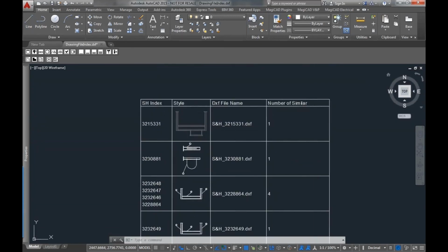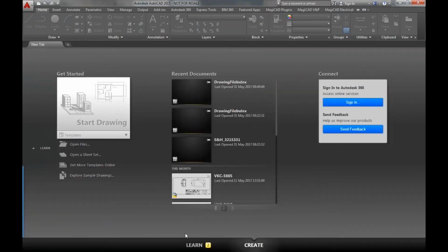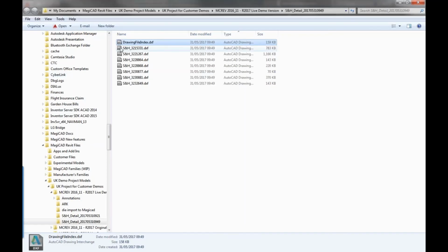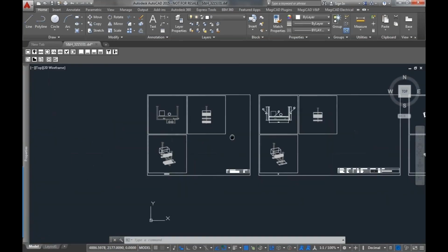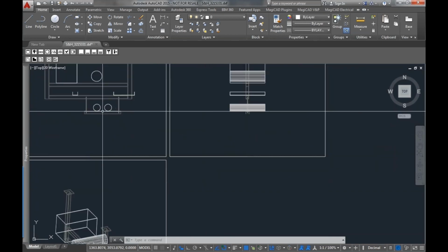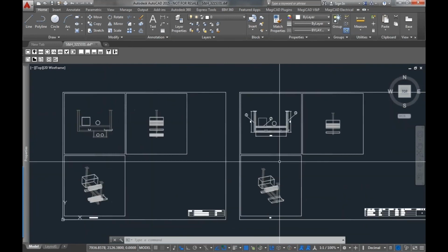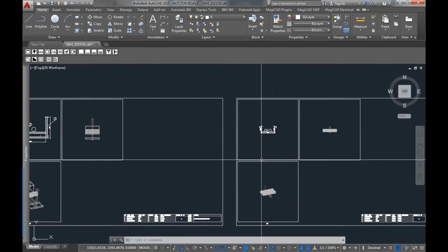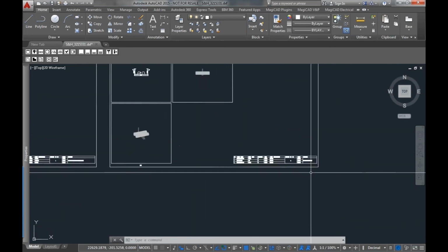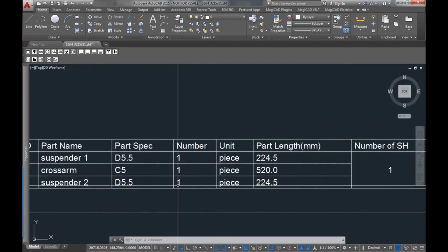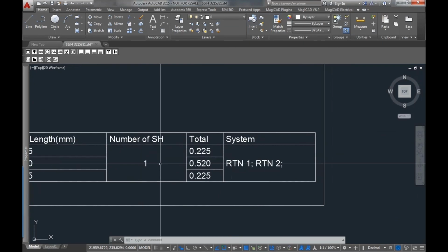And then if I go into the actual drawing itself, you can see there's the integrated hanger, there's the isometric we wanted off it, and there's the individual components that make up that supporting hanger as well, with the key showing you the part spec and the number of part length, etc. So you can build up all your supports and hangers fabrication details from that tool fairly easily.